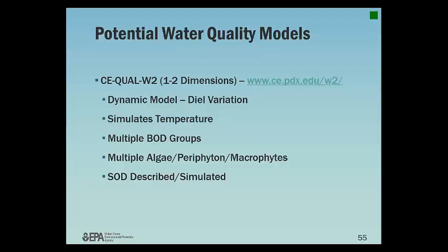It simulates temperature, has the capacity to model multiple BOD groups, and can include the impacts of production and respiration from multiple algal, periphyton, and macrophyte groups. You can describe the SOD rate to the model or have it simulated as a function of a sediment diagenesis model. The model can be downloaded from the website listed.